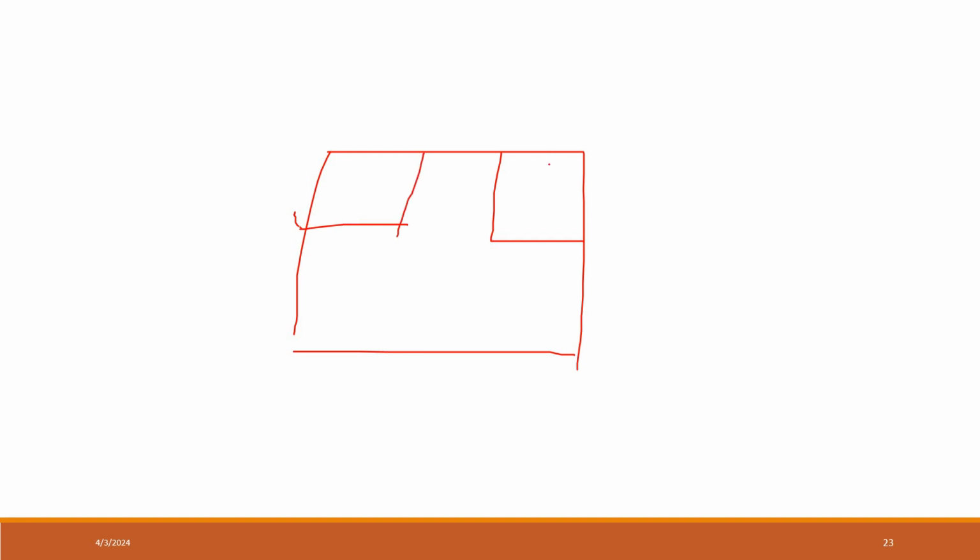This is our structure basically. This is drain. Where are we defining the code? Here, electrode here. So here X thickness is 0, Y thickness is 0 to 10. Okay. And same electrode for source we are defining here. X thickness is 0, Y thickness 10. And gate electrode from here to here means X 0 to X 50, Y becomes 0. Means I am considering 0 thickness of electrode.